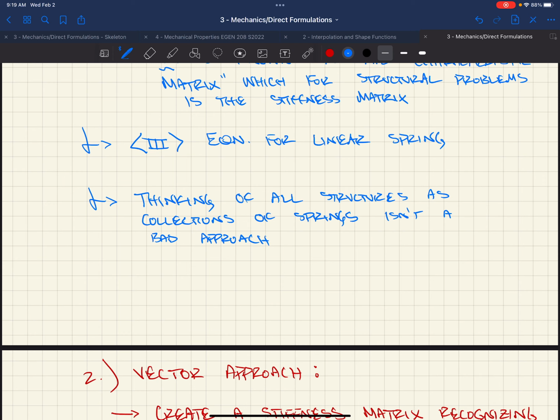Lateral elements could be continuous from the roof to the basement level at the very bottom. But the stiffness of the diaphragm can sometimes dominate so much that it is pulling load out of a brace frame and putting it into another one, because it is stiffer than the brace supporting that brace frame below itself.